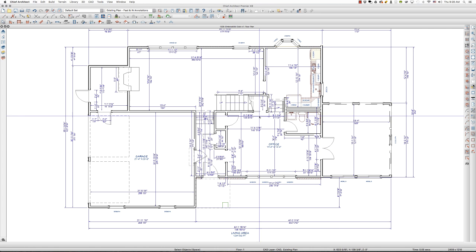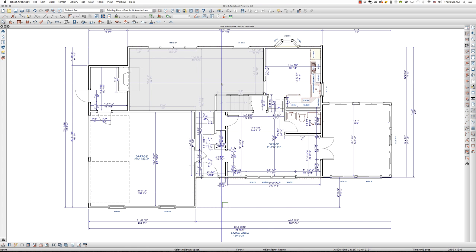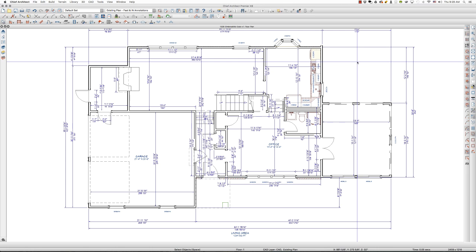All right, so that's a quick tip on using Match Properties and changing things quickly. You can do that with floor and wall materials. You can do it with heights and widths of windows and doors, cabinets, etc. It's a really great tool to apply and propagate those numbers and materials, styles, etc. across many different objects.